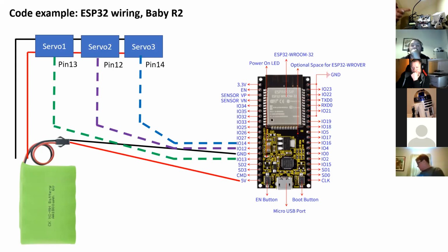Now, what I would say on these, while we're talking about them, you've got a little button there which you can see says boot button. I think it's the boot button that you press, isn't it? Yeah. On the ESP32 that I've got, where you would normally click upload to put the code onto the Nano, the ESP has one extra step, which means that the boot button has to be pressed before it will accept code. If you try to load the code as you would with a Nano, it won't take it. So what you've got to do is load the code, press the boot button, and as long as the boot button's pressed down, it's in that "give me your code" state, and then it receives the code. These will also allow you to load the code via Bluetooth, and you can do it over the network, but you can do it through a standard USB as you would normally.